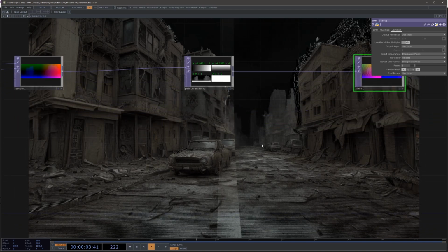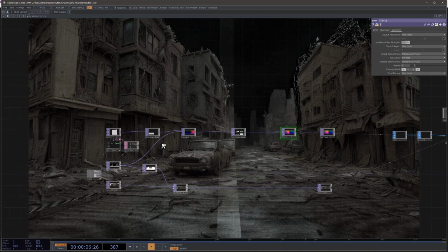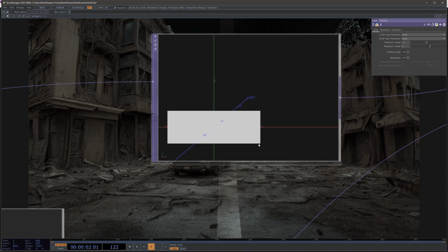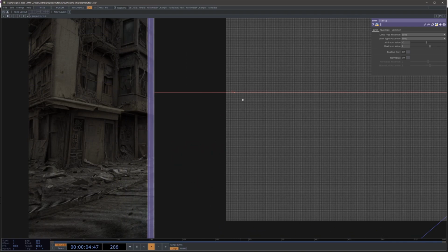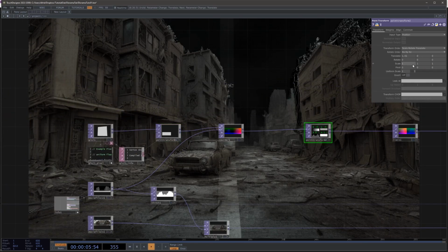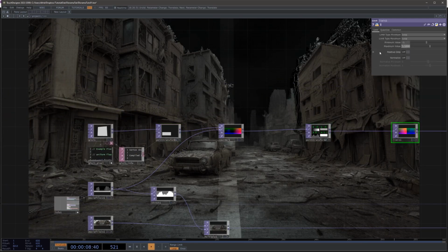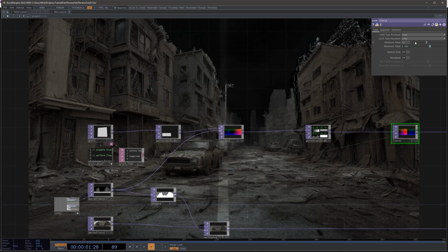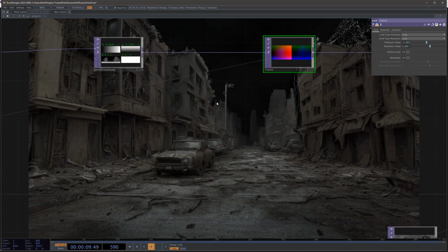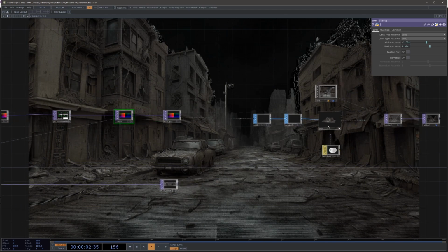And right now you can see they are kind of overlapping. It's because we put the limit to -1 and 1, but actually our grid is not exactly going from -1 to 1, it's minus scale divided by 2. So let's copy these parameters into the limit. In the maximum value, let's add this one, divided by 2. And same for the minus, we divide it by 2 as well. And so right now, it's perfectly fitting and sitting right next to each other.